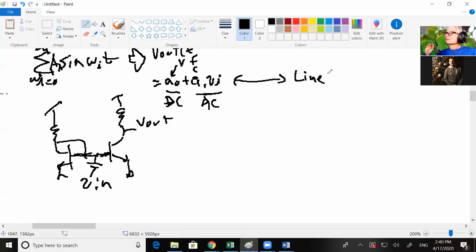And if you remember back to circuits 1, there's a particular technique that requires your circuit to be linear, the components being linear. You remember that analysis technique where you needed everything to be linear? Thevenin's analysis? Norton Thevenin stuff? We'll use that later, but that's not what I'm thinking of right now. Superposition, maybe? Superposition, exactly. So if all the components in your circuit are linear, then you can use superposition.